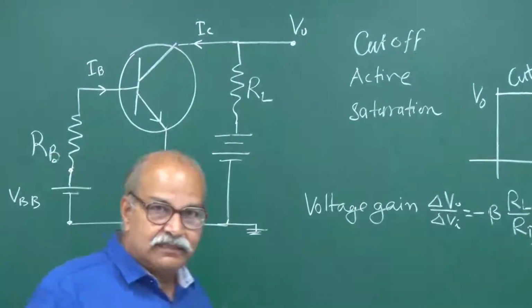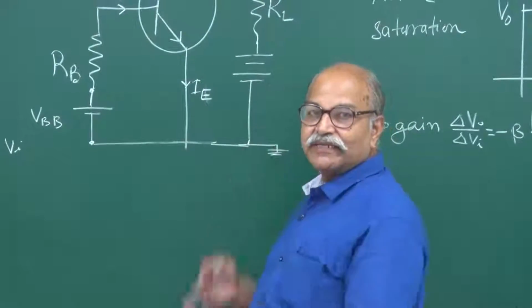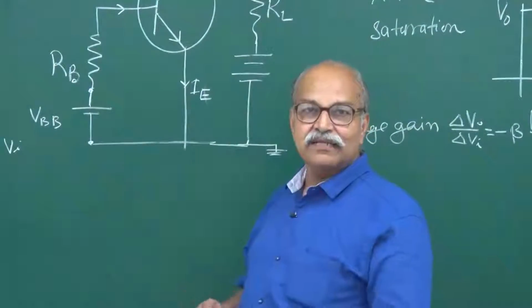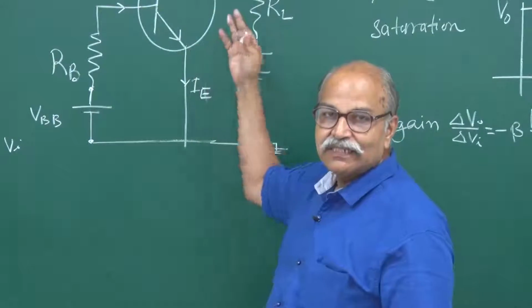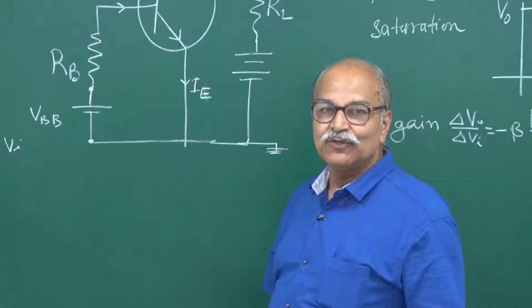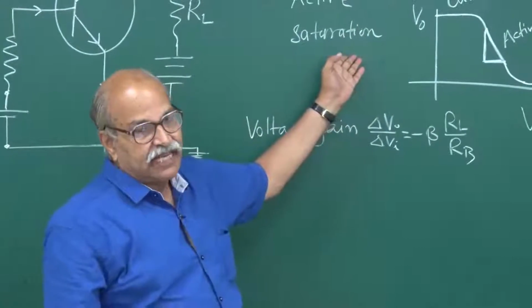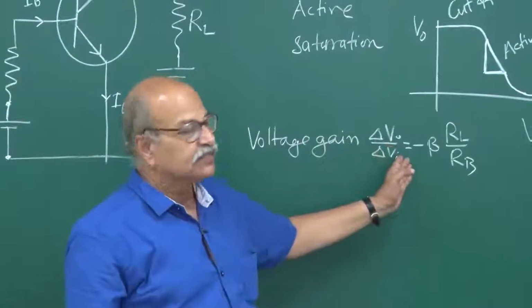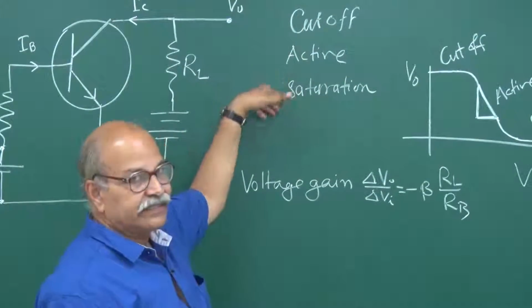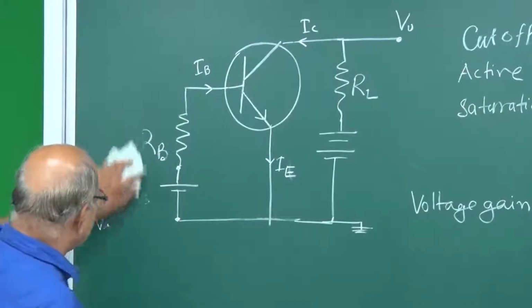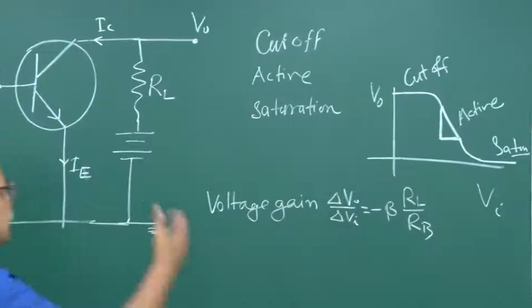So today's agenda is to perform this circuit on the table, to take a real transistor, batteries, biasing, resistances, do this circuit here, measure the values and see where those 3 regions are, and then if time permits, about amplification. But today we will mostly concentrate on the cutoff, active, and saturation regions. Before that we have to change this VI, and then we will see all those regions.